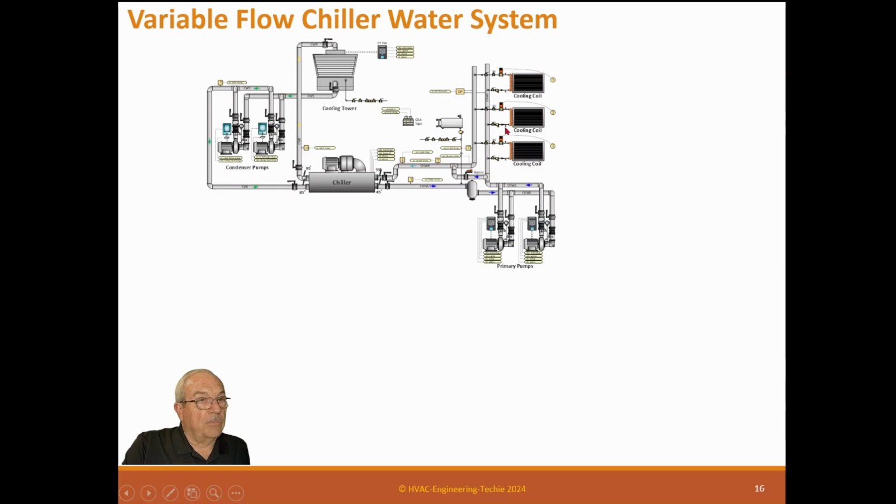And these are variable flow. So as the flow starts to cut down and the flow goes down through the chiller, it's not a problem, except variable flow chillers will not accept flow below 50%. They need to maintain at least 50 to 100% flow. Below 50%, you start causing problems with the chiller. So what we do is we put a bypass in to make sure this always has 50% flow. Now, manufacturers have always recommended you put a differential pressure sensor on this bundle to run that valve, and I tell you, don't do that.